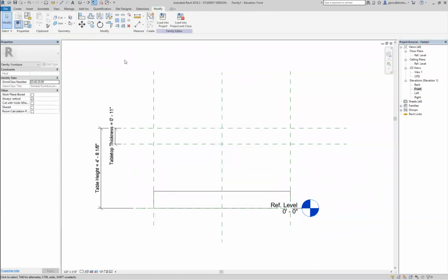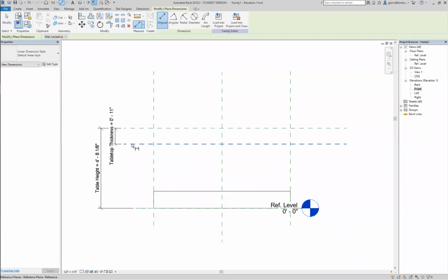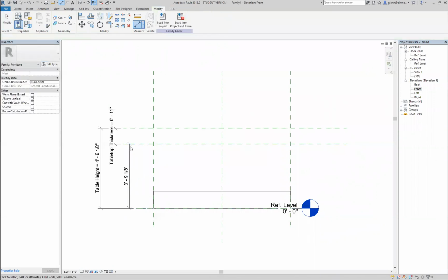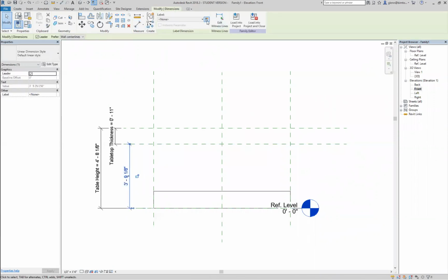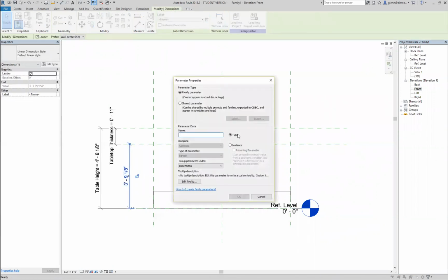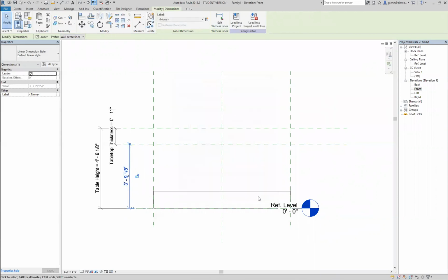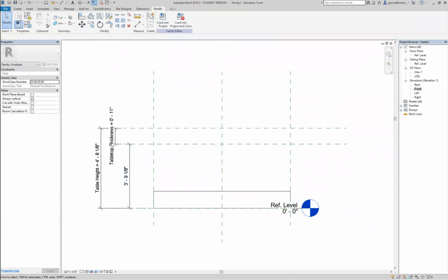Super. Now watch out, if I try to add a dimension here to here, it'll report that. But if I try to add a parameter to it, it'll over-constrain things. You don't want to put a second parameter in there because you can't have all three of those be parametric. Two can, but one has to be floating as a degree of freedom. So we'll leave that as just those two.